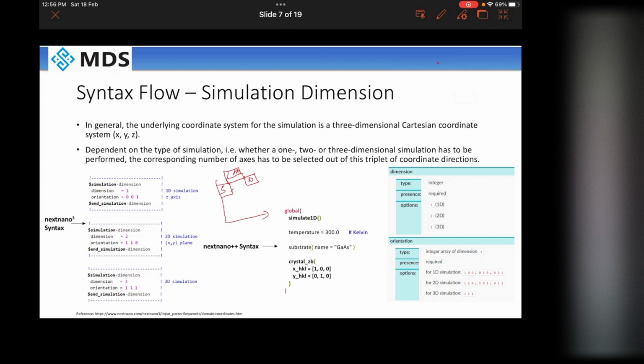So throughout, the concentration or the structure is not similar. In that particular case, you should start with 2D. 1D is not a solution. If you just want to see the MOS cap, then you can take a 1D cut line and check how much electron concentration is there in the channel part, or whether it's depleting or not.